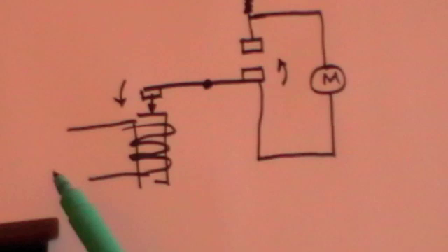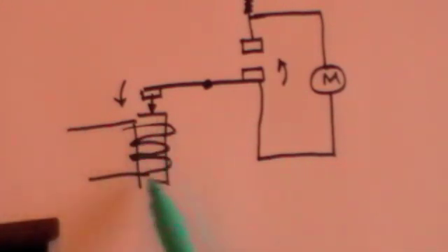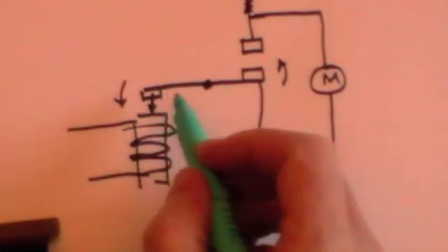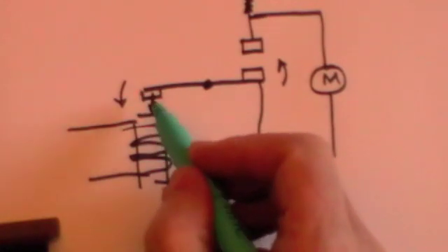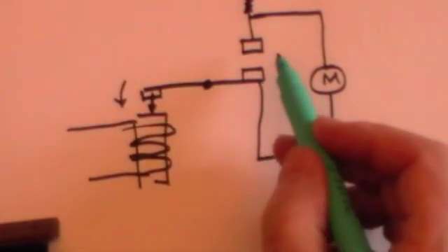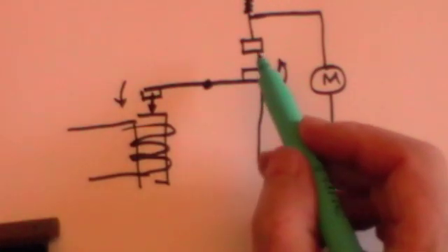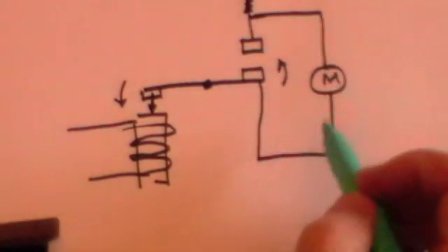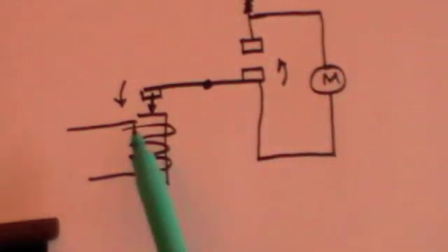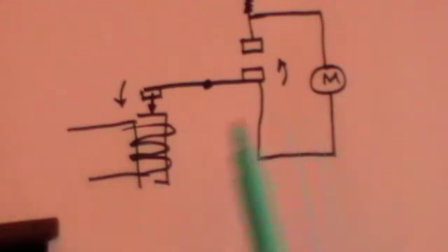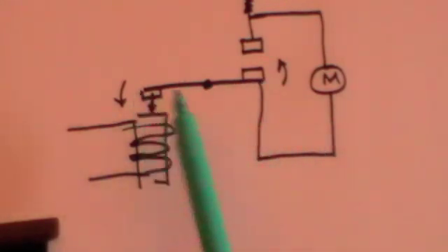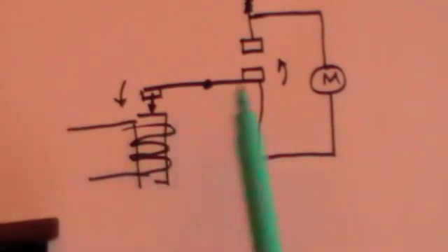But when the logic circuit is satisfied such that all the conditions that we set out before are satisfied and you get an output, the output will cause the solenoid to become a magnet. The magnet causes this part of the arm to swing down because the magnet attracts the piece of metal. That in turn causes this part of the arm to swing up, and now the two contacts meet, and this now is a complete circuit and the motor comes on. But notice that electrically the two circuits are entirely separate, and they're kept separate by this bar, which is insulating material, so no current can flow between the two. And that is called a relay.